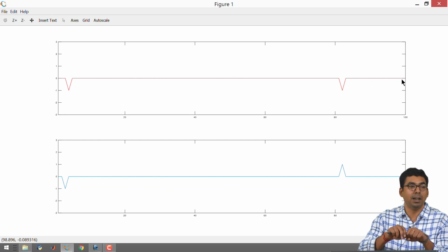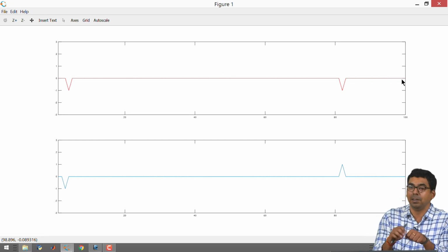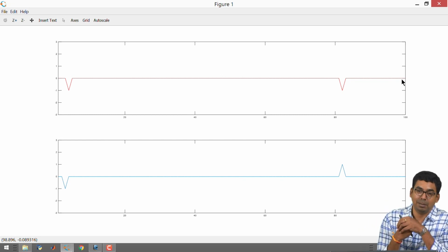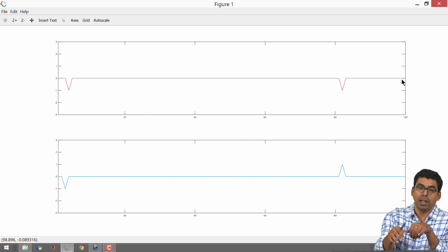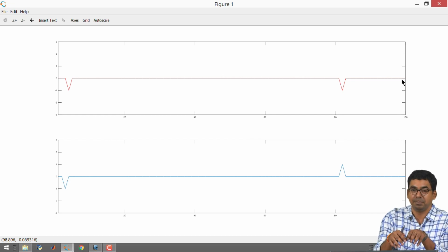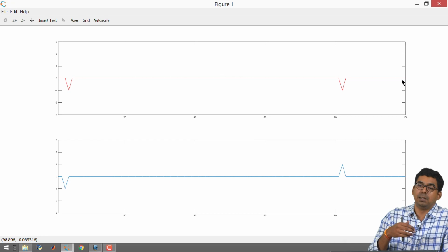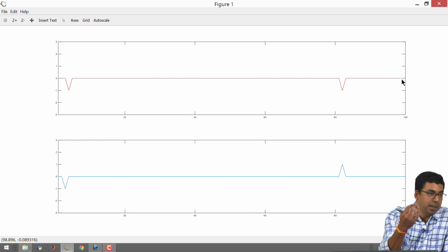Maybe the transmission line is broken, or maybe the insulation is breaking down and something is shorting the forward and the backward conductor, all right. If we know the location and if we know the kind of fault that we are looking for, then it makes it easy for us to go to that particular place and fix something. Okay. So what people can do is they can take a transmission line, launch some voltage from one side, wait for the echo from the other side.